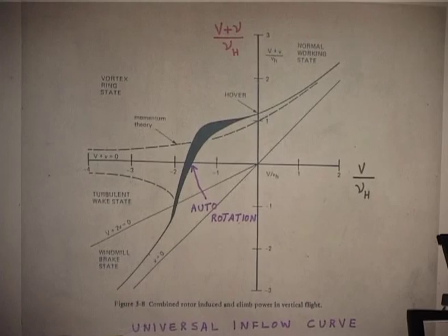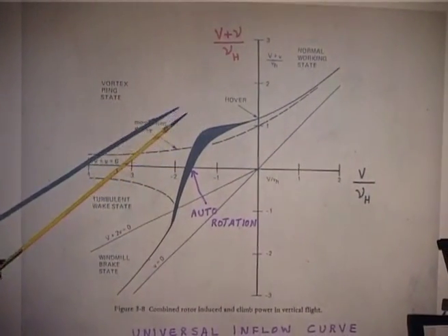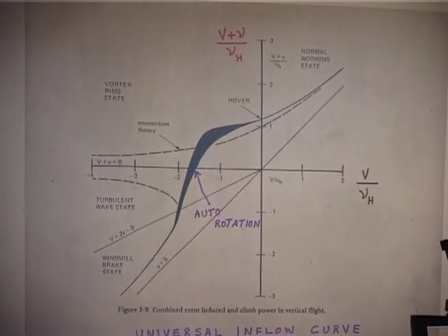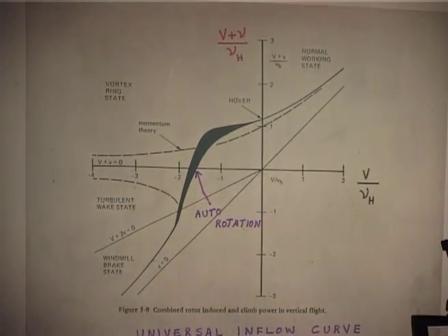Now you see this is not that easy. Right at the very simplistic level of the introductory course itself, you will know that there is something in this region which you can't calculate. That is where the experience, industry, tests and measurements come in. Of course, pilots go through a little bit of auto rotation experience in flight. Not that they will come and land, they do not do that. They will just do a power off and then try it, because that is a maneuver they must learn. We will do a little bit on that, because auto rotation is very interesting.